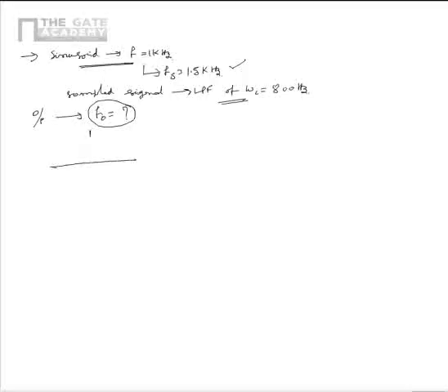We know that the Fourier transform of a sinusoid contains two impulses at frequencies plus and minus 1 kHz. Here the frequency is in kilohertz for the frequency spectrum drawn. Now, this signal is sampled at a frequency of 1.5 kilohertz, because of which we will see the repetitions of the frequency spectrum shown, and the repetitions are centered at multiples of 1.5 kilohertz.